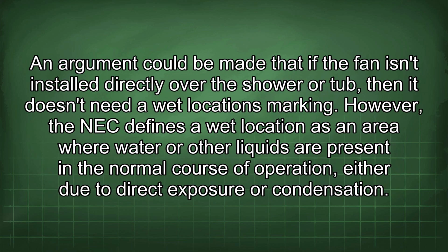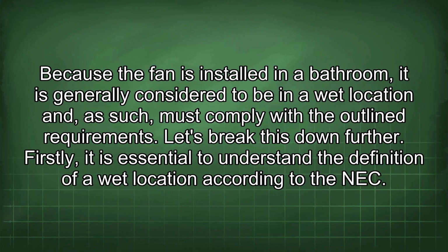An argument could be made that if the fan isn't installed directly over the shower or tub, then it doesn't need a wet locations marking. However, the NEC defines a wet location as an area where water or other liquids are present in the normal course of operation, either due to direct exposure or condensation. Because the fan is installed in a bathroom, it is generally considered to be in a wet location and, as such, must comply with the outlined requirements.